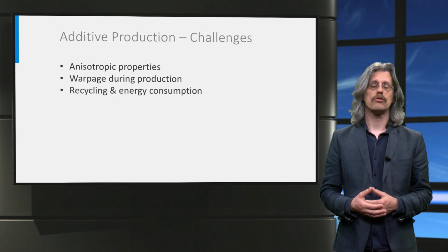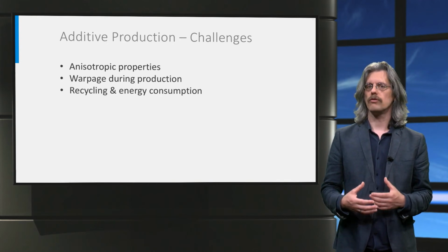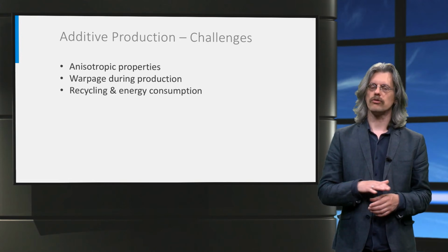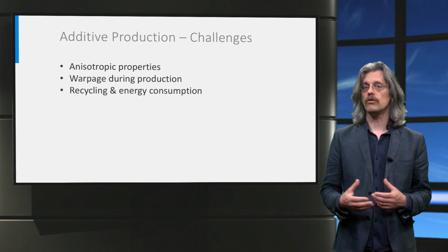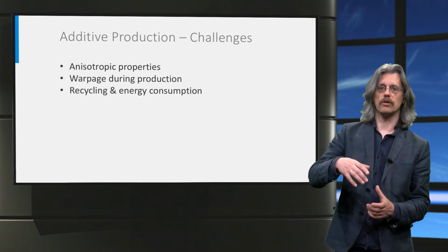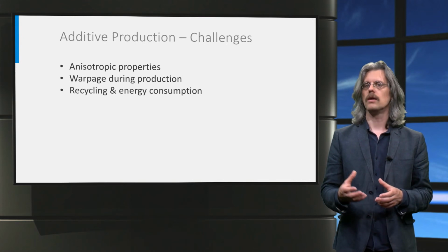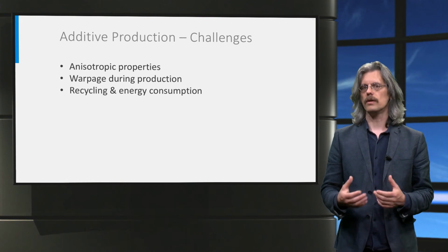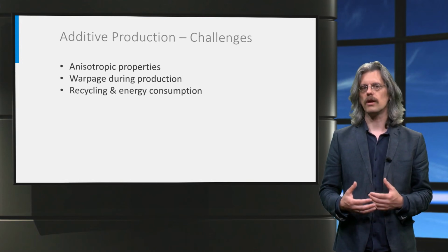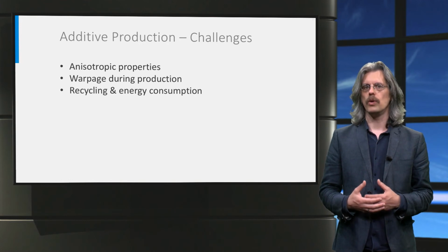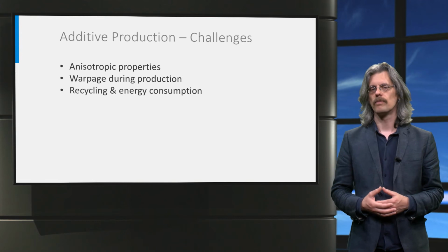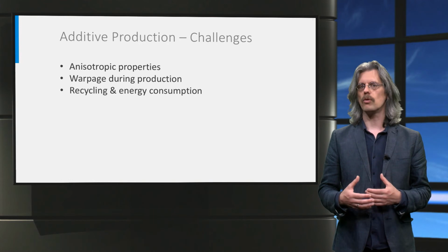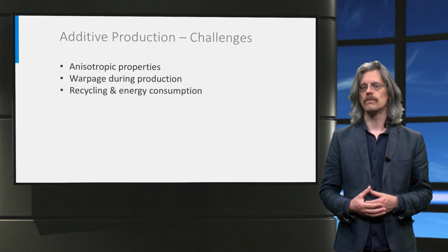A second problem arises from residual stress during the solidification process. This might lead to deformation while subsequent layers are deposited among each other. This is often solved by adapting the build-up orientation and, if necessary, adding additional support structures to minimize warpage. Finally, although 3D printing represents an exciting manufacturing solution, we know little about its environmental impact. Specifically, the recycling and energy consumption during manufacturing and the logistical processes should get more attention.